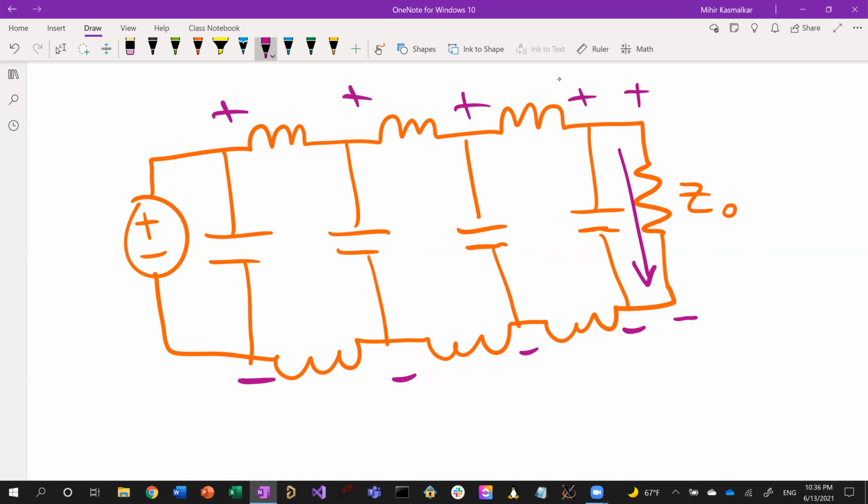Again, from the voltage source perspective, there's no difference between a resistor of value Z0 and a lossless transmission line with characteristic impedance Z0. And so you see the wave sort of just stops here, but it continues flowing. This is, again, the exact same as if you just had a battery and connected a resistor across the leads of the battery with a value of Z0. You see current flowing through this resistor, a voltage across this resistor.